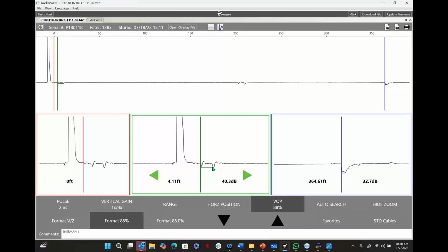And then they say, didn't you say you found another problem just a little further in? I said, I did. Now I'm feeling confident. And I'm saying, yes, I did. It is at 9.74 feet. So if you're keeping track at home, we had just about 3 or 5 feet out of a water sprinkling system, right? So we go in just a little bit further. We dig the hole. Full disclosure, we saw nothing right there. So we got to make a choice. We're going to dig a little further this way, dig a little further this way. We went just a little bit further that way, and sure enough, we found the splice. That was undocumented. I bet that never happens, right? And we go a little bit further, and we see this splice.